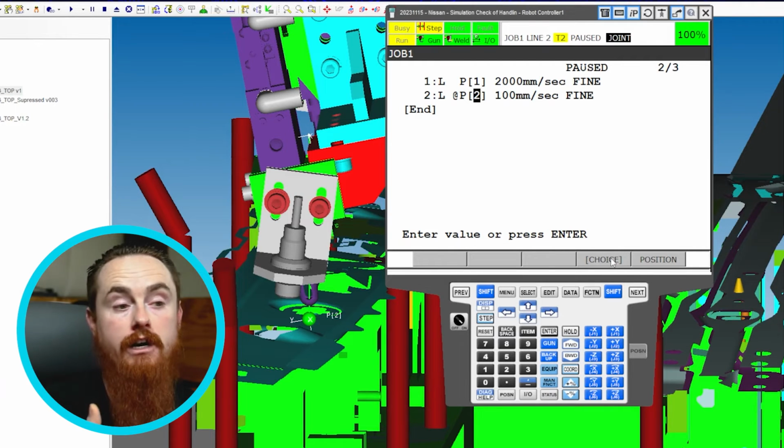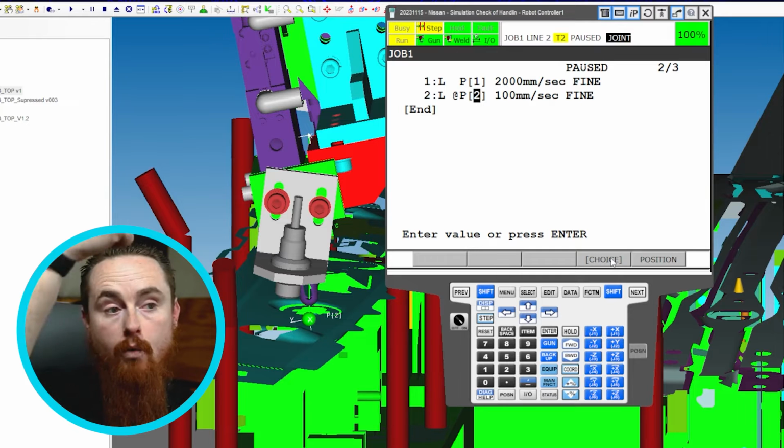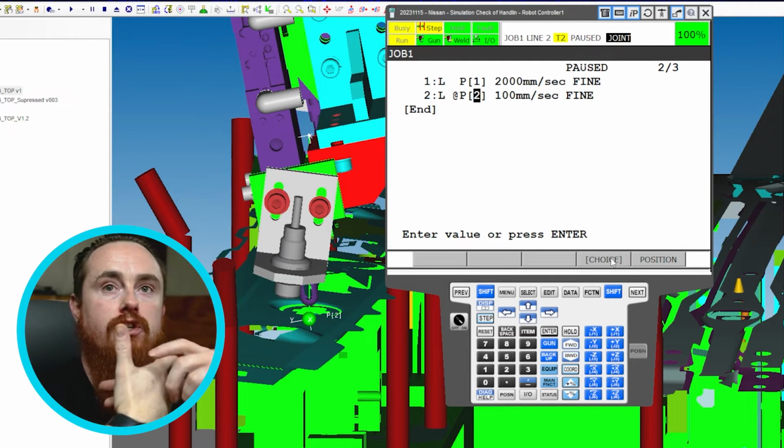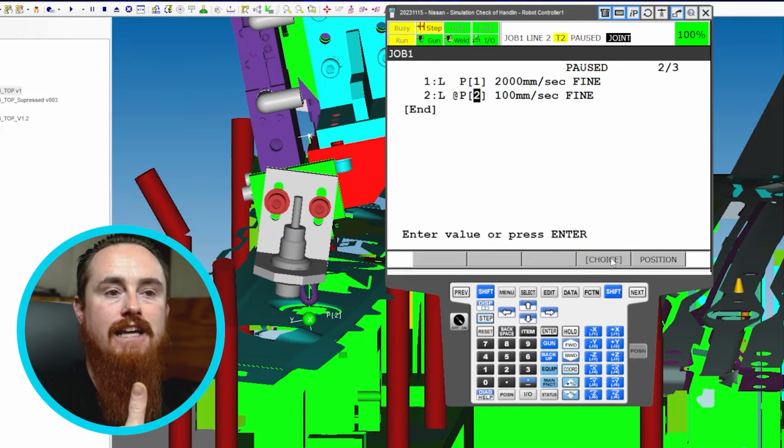This is when you're moving in a downward motion too, right? So when moving down, your X and Y need to be in the same positions because you want to move down in an exactly straight line. There's approach positions, I want to add this caveat to this. If your approach position is inside of something, like if you're going this way, so your approach is here and then your at position's inside, then you need to make sure your Y and your Z are the exact same. So you got to think about relative to which way you're going.